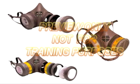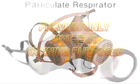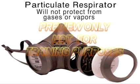There are three different types of air purifying respirators: a particulate respirator, a combination respirator, and a gas and vapor respirator. A particulate respirator captures particles in the air, such as dusts, mists, and fumes, but will not protect you from gases or vapors. This type of respirator generally becomes more effective as particles accumulate on the filter and plug spaces between the fibers. A common dust mask is considered a particulate respirator.